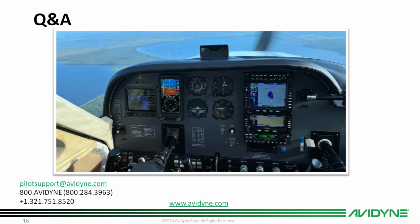So the IFD does have an en route VNAV capability with the latest software, but the VNAV capability on an approach depends on the autopilot. We output the protocols for it. It just depends on your HSI and your autopilot. Some autopilots only have a lateral feature, and some have a glide slope capture. So it just depends on the autopilot.